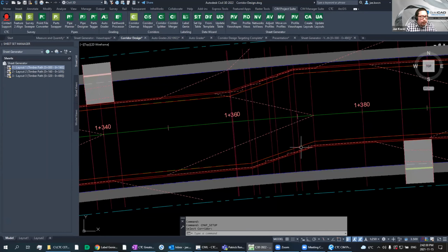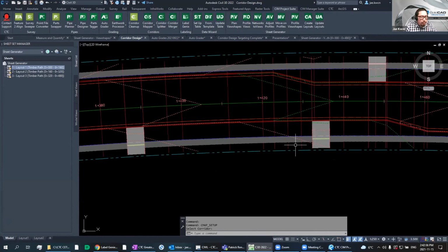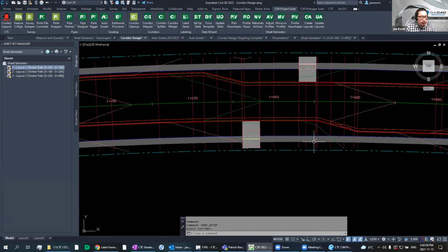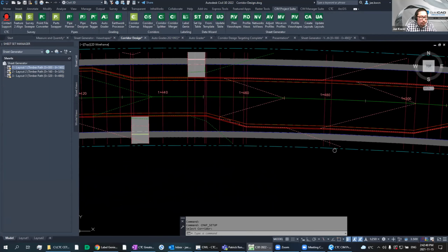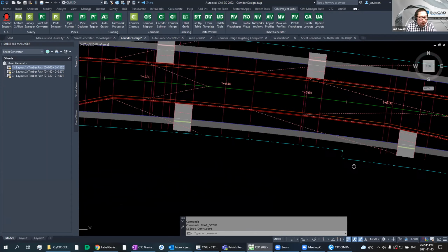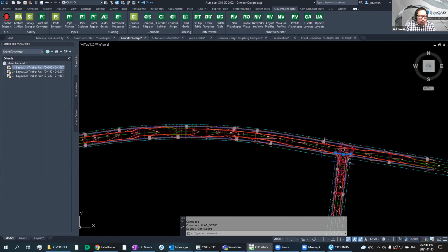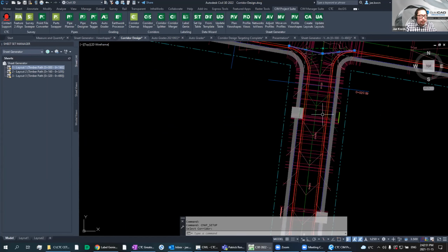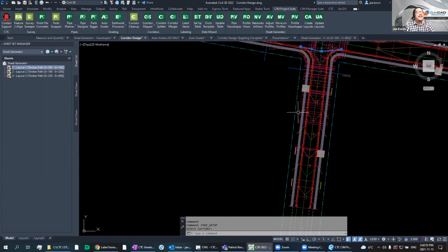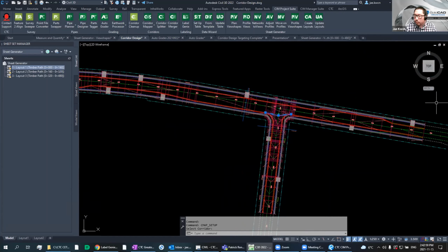So the lane is following the lane offset target. We're cutting the driveway where we need to. The boulevard, the outside edge of the sidewalk is where it's supposed to be. And the last little slope, or lane slope, or the generic width and slope one, that's targeting the right of way.